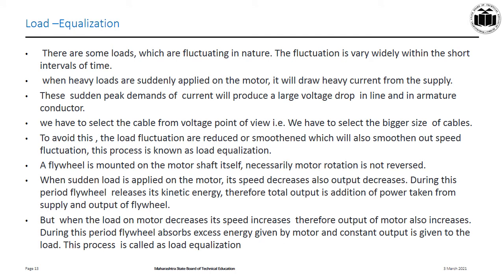Till now we have learned the different types of rating, but now we will see the concept of load equalization. There are some kinds of load which are fluctuating in nature. The fluctuation is very wide within a short interval of time, from very high to low. It goes on. So when heavy loads are suddenly applied on the motor, it will draw heavy current.